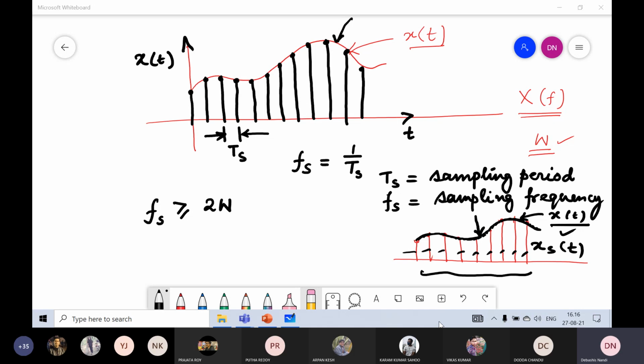After amplifying the signal, if you see some other noises are there, then you have to filter that noise by using a filter. At the same time, the signal cannot be frequency limited at all. I told you that frequency limited means band limited. If a signal is time limited, it cannot be band limited. But when I am singing a song, that signal is time limited. For a fixed time you are singing a song and then it will be converted into digital format. That means for a certain time the signal is present, and outside this time it is not present. Therefore that continuous time signal is a time limited signal. It is not spread up to infinite time.